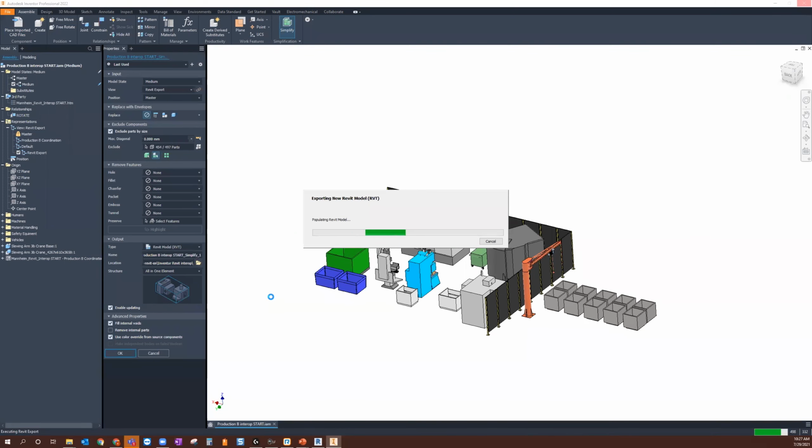And I don't know if you touched on it earlier, Jeff, but if I wanted to edit the original import that I did, maybe take a few layers and items off, could I still do that as well? You definitely can. You always have the ability to update and remove some of the Revit families or the Revit categories. What Revit calls them are elements inside of that imported model.